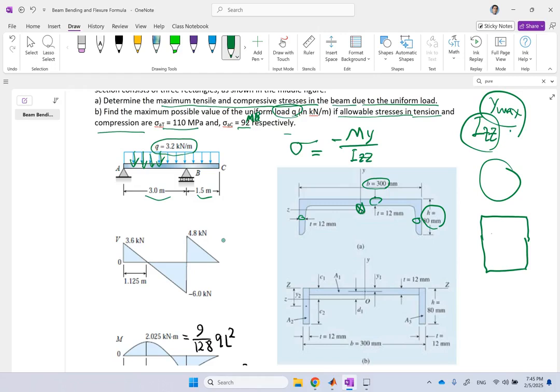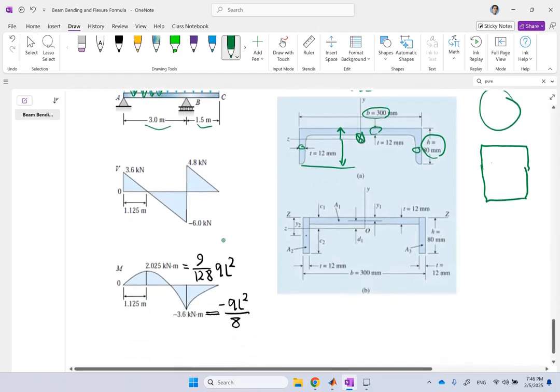That is clearly going to be a constant number. But M and Y are variable in this beam. Not only Y is variable, you can go from this point up and down. You can also see that M is not constant. If you plot the bending moment diagram versus location, M is not going to be uniform. M actually does change because the shear force is non-zero.